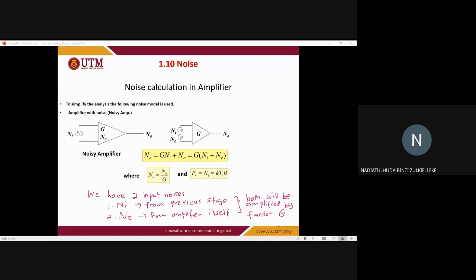We have a question here. You mentioned impedance matching. What is the significance of it in relation to the noise and the load? Impedance matching is when R from our noise source is equal to R at the load. In this condition, when they match, noise power is equal to the power at the load. If Rn is not equal to RL, if they don't match, then you do not get the condition of Pn equal to PL.